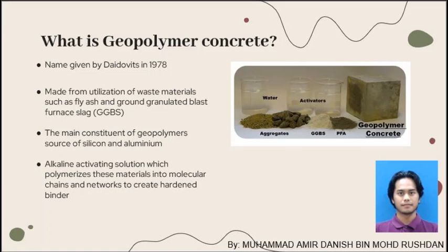What is geopolymer concrete? Geopolymers are in the family of mineral polymers in which their chemical combination are similar to zeolite materials, whereas their macroscopic structure is amorphous rather than crystalline. The use of polymers such as concrete adhesives result in the production of geopolymer concrete that can be a suitable substitute for OPC, or it is known as ordinary Portland cement.